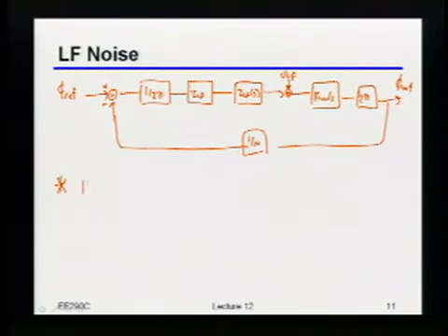If I do the transfer function from the loop filter voltage noise, it's just the transfer function from the reference, but now we have to normalize it by something else. So now we're normalizing it by, again, 2 pi over our I charge pump, but now we have one more additional gain block, where that gain block is the impedance of the loop filter.